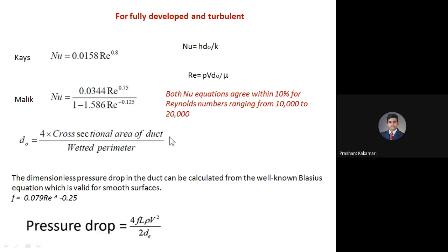So here, finding the cross-sectional area of the duct is easy because it has some height and width. That is the cross-sectional area. Then the wetted perimeter: perimeter is nothing but width plus height of the duct, so one can find that. Area one can find because it is a rectangular section; you can find the product of width and height of the duct.